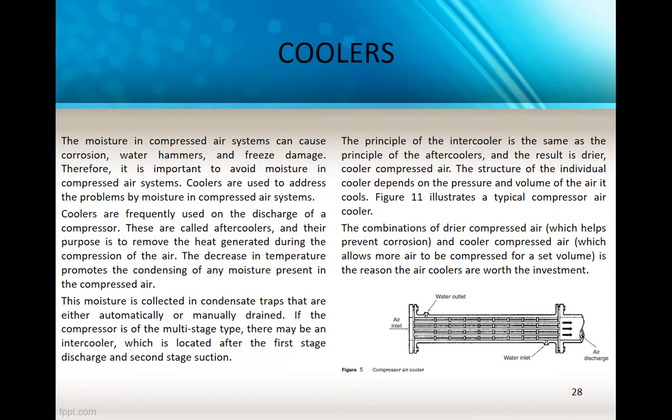If the compressor is of multi-stage type, there may be an intercooler, which is located after the first stage discharge and second stage suction. Alam itong intercooler, di ba? Intercooling sa compressor. Yan. The principle of intercooler is the same as a heat exchanger, and the result is drier, cooler, compressed air.